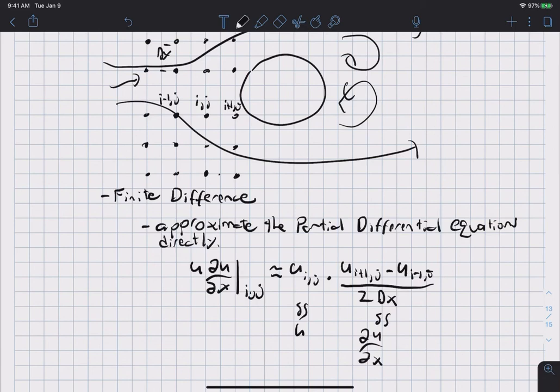And so with finite difference, you just basically lay up a grid of points, and then using the data at each of these points, you go and approximate all the terms in the Navier-Stokes equations directly, and then just solve. Now, there are a lot of games you have to play, and there are a lot of other details. But that's the basic gist behind the finite difference technique.